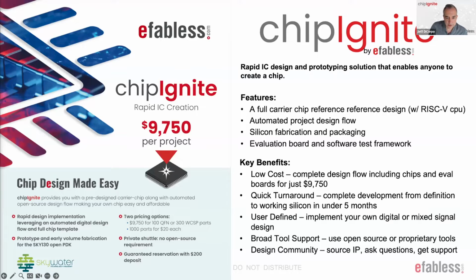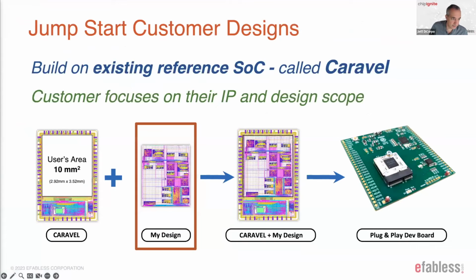The way this works is you leverage a pre-existing chip called Caravel. This is a pre-built, pre-designed SoC where you can take your custom design, your custom circuitry, and integrate and implement that inside of Caravel to get to a custom part of your own, with your own design implemented.